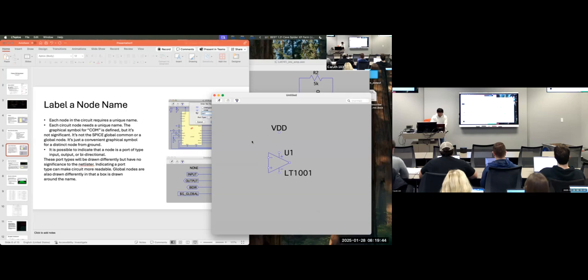Okay, so I'm going to wire. Right click again, go to draft, and the first thing is wire. Now we're given this little crosshair. I'm going to click the little part, drag that down directly to the plus sign, and wire it. Now VDD should rotate automatically like that, which is a nice indicator that it is wired properly to the plus part.